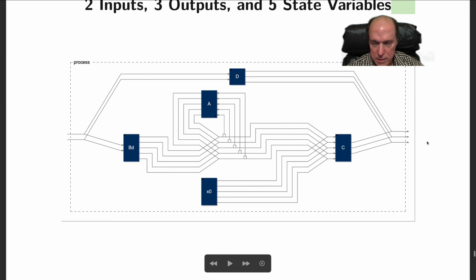x0 plus B plus U, D times U. And then after that, you're looking at the input through B, and the output is C times the feedback. I'm about to say the transfer function, but I guess I could say C times (sI minus A) inverse, or (zI minus A) inverse times B, but that's not fair because I haven't derived that for you. But you can see right here what it's doing.